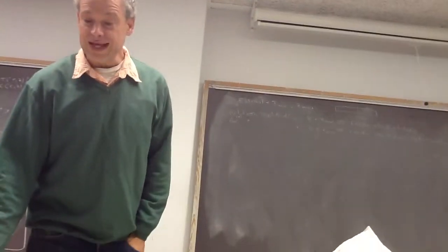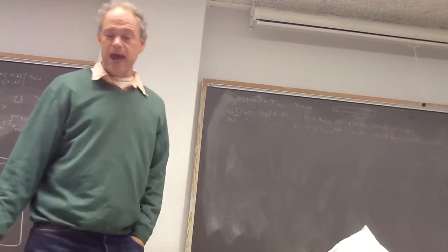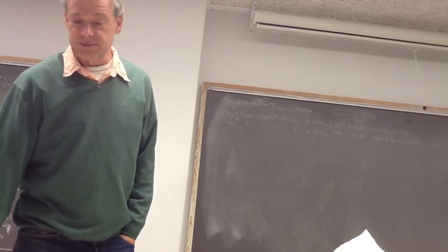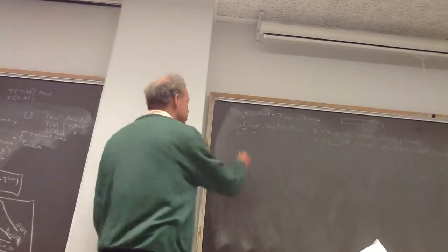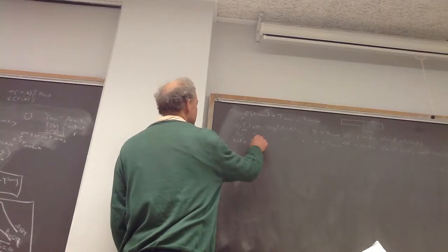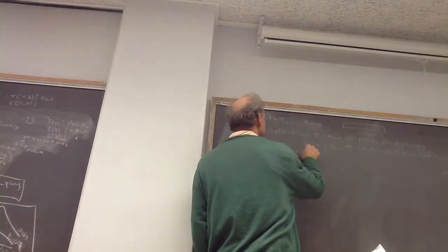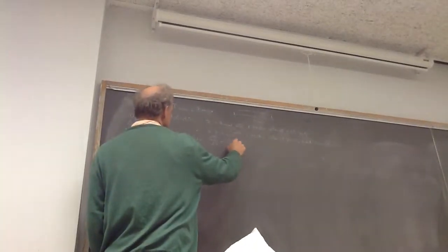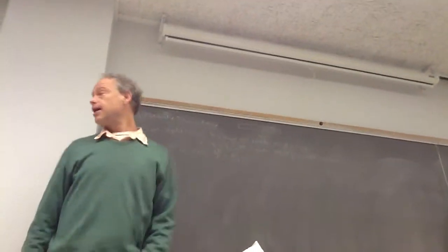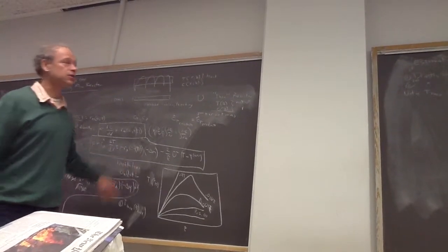Okay, so that's the basic assumptions. And let's see what happens when you do that. Let's do the analysis. Well, actually, there's one more thing. Where does Tmax occur? Note, Tmax occurs when dT/dV equals 0, and dT/dz equals 0. That's the maximum. And when dT/dz is 0, the heat transfer balances the heat generation by reaction.